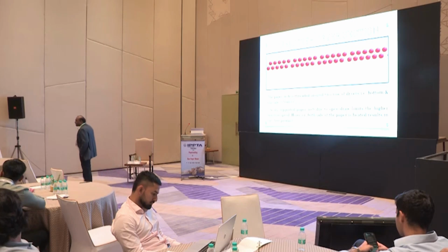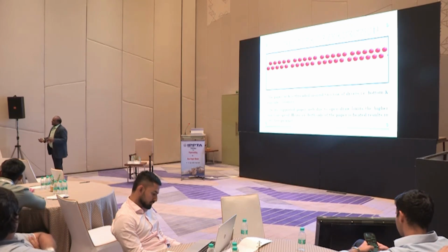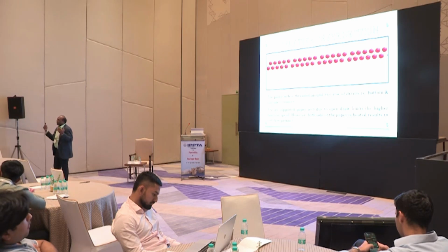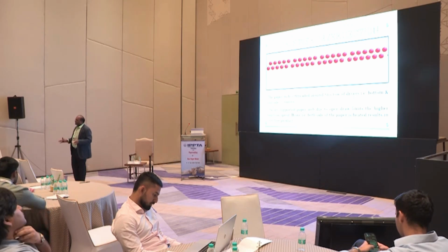Yes sir? Sir, if you are adding more dryers it will be better, because it will be drying quickly and the machine speed can be increased. No, that is different, sir. The number of dryers will help only in quick drying and increasing the speed. It will not play a role in shrinkage. Anyway it has to shrink. Even if you put thousands of cylinders, the paper will get shrunk. We cannot avoid the shrinkage. It is a natural process. Is that clear?